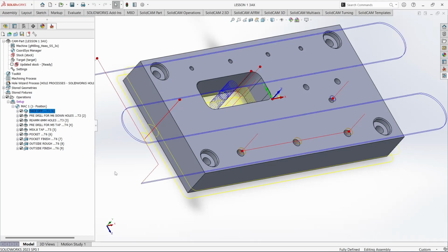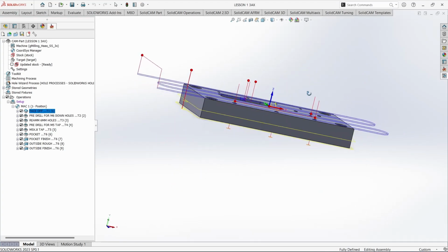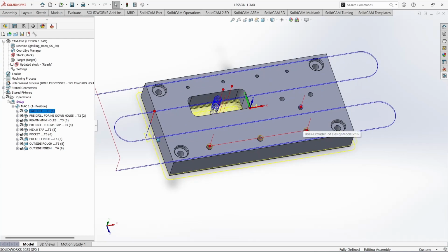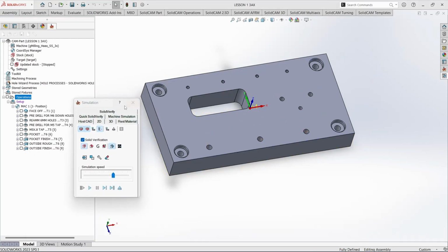Okay. All right, so all the toolpaths show up here. Everything looks okay. I mean, of course, when you run on the machine, then you adjust it. But with the program, it should look like that. And now, fun part, right? Render it. If you want to render individually, then you just select that. But if you want to render the whole thing, you just do simulation.